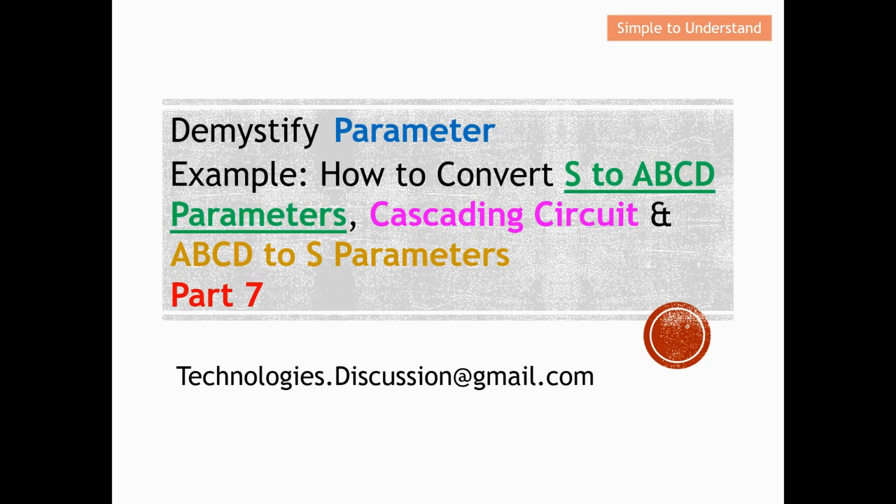In short, this video will show you why we need to convert parameters from one form to another form. For example, in this video, you can see that I convert the S parameters to ABCD parameters. After that, we will utilize these ABCD parameters to cascade the circuit. And then last but not least, we will convert the overall ABCD parameters to overall S parameters. So this will be the objective of this video.